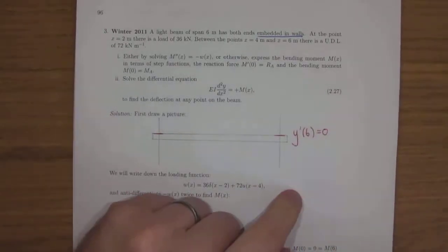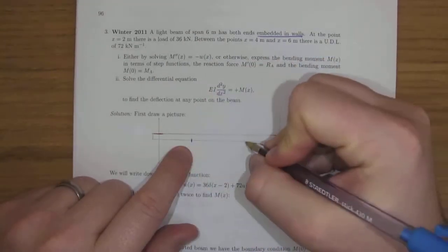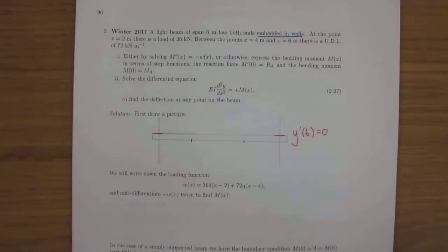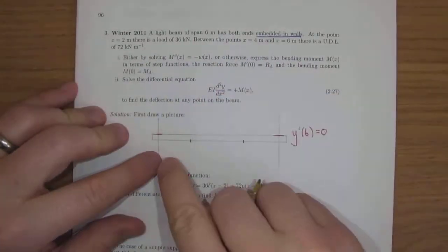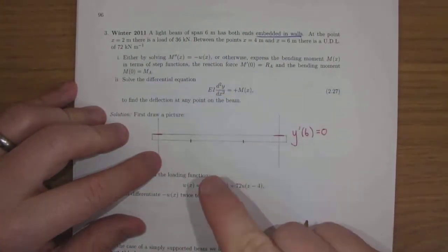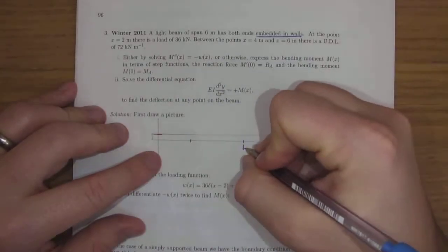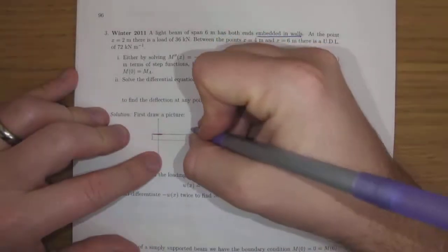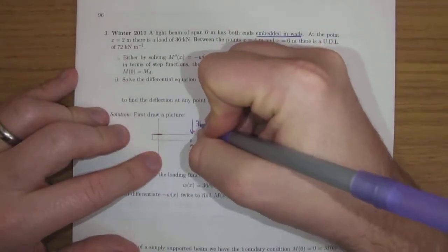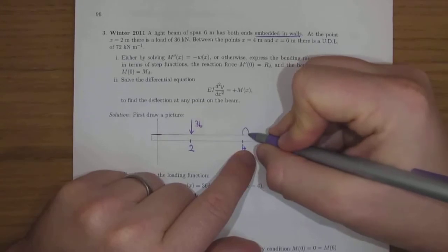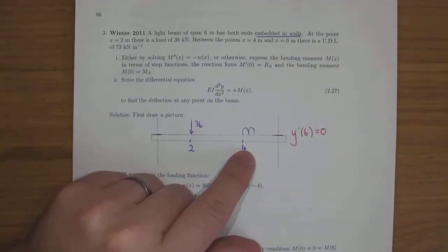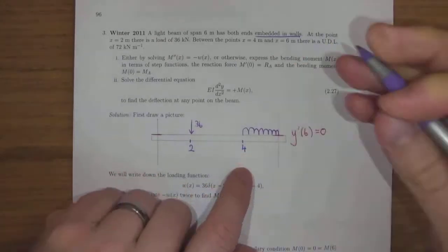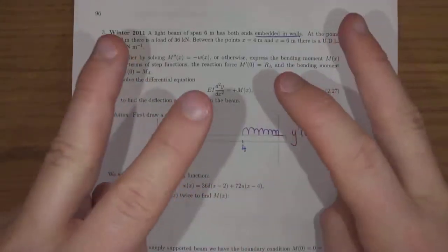Let's draw our things. So x equal to 2, x equal to 4. I don't really mind how you annotate them as long as everything is coming out right. Some of you might put 2, 2, 2, but for the way we're doing it here, it's probably better to put that 4 and a 2 there. We have a point load of 36 kilonewtons and a UDL of 72 kilonewtons per meter from here to the end of the beam. And as we said, if it goes to the end of the beam, you don't have to turn it off.